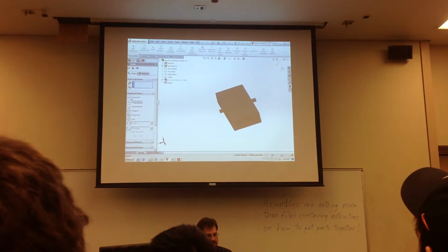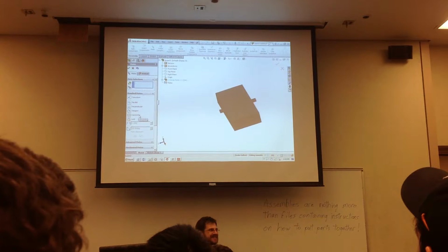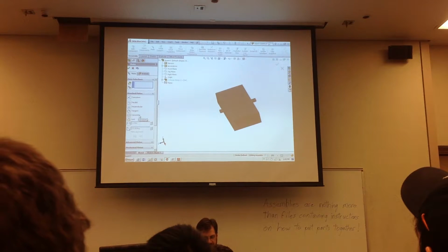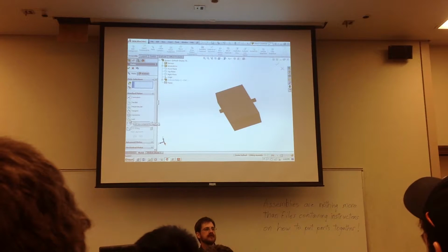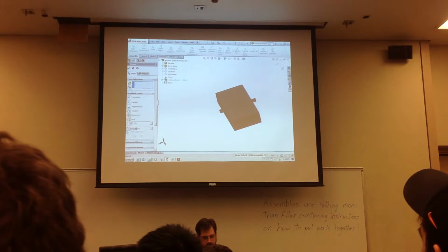You can make things coincident. You can make faces or planes parallel to one another, perpendicular, tangent, concentric. Concentric just means that two curved entities will have the same center point or the same axis. There's an option called lock. I would recommend that you never use the lock constraint, because that causes more problems than anything else. Avoid using the lock constraint. But you can also specify an offset distance or an offset angle. Those are very useful.